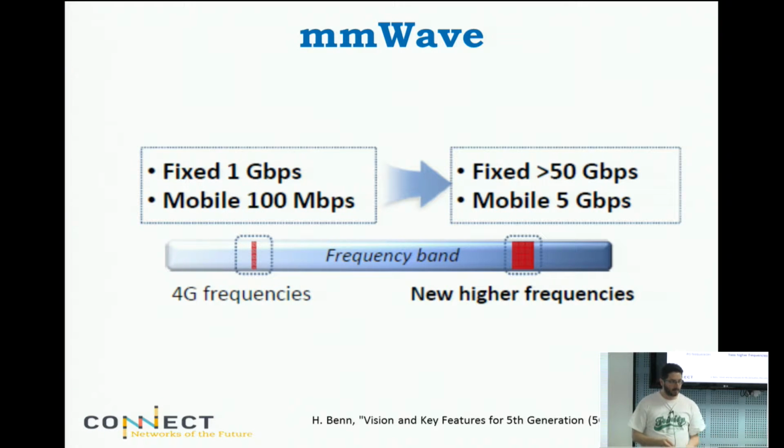There are some catches though, of course. The propagation is somehow limited, right? You cannot go that far with the signal at millimeter wave, because we know from physics that the higher the frequency, the shorter the range of your signal. It attenuates faster with distance.